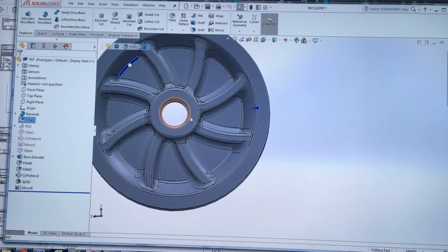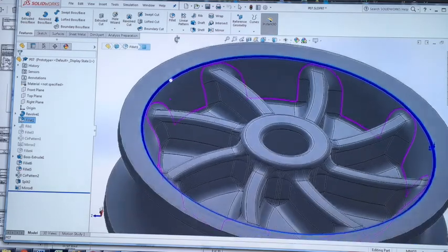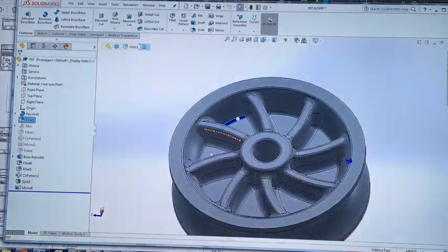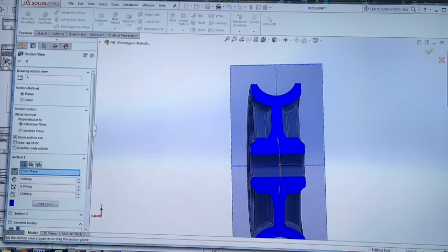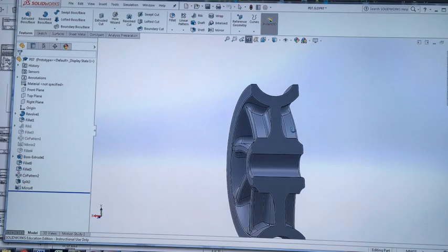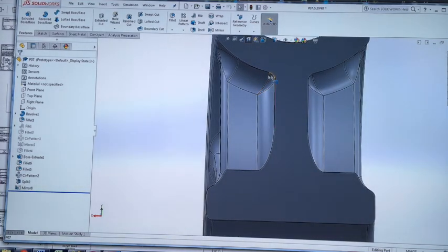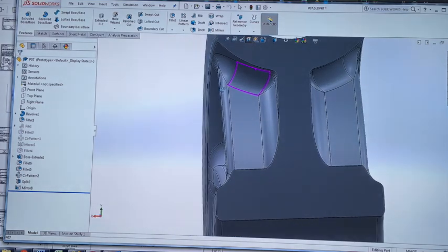Okay. So these little ones here, firstly, they're external, no problem. These ones here are a potential issue. Let's do a section view. So here is the problem, okay? When we're coming down the corner, that's a nice large radius, 2.5, that's fine.